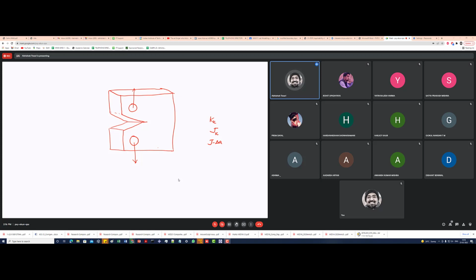So for instance, if you remember our previous course on mechanical behavior and testing of materials, there we spoke about the crack being a singularity, and there is a plastic zone associated with it, which in mode 1 has a shape of this, right? So this is the shape of von Mises stress, and when von Mises stress is higher than a certain value, which is your yield strength, then you can say that the plastic deformation has started.